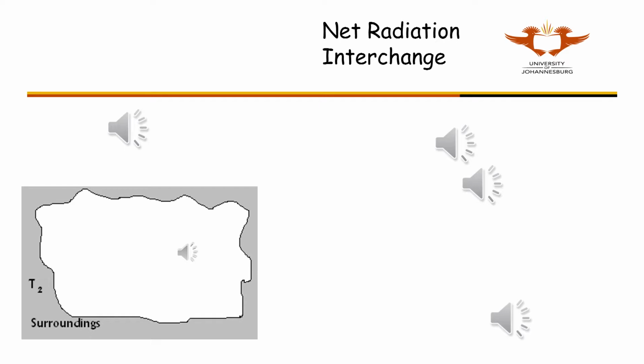Consider a large non-ideal enclosure at a constant temperature T2, i.e. steady state conditions. Heat emitted by the surface will be equal to heat absorbed by the surface. Further, assume that the surface is gray, so that the emissivity and absorptivity are equal. This is probably reasonable, as the radiation is generated at the same temperature as the radiation is absorbed. See the literature on non-gray surfaces. The absorptivity and emissivity are different due to temperature differences of the surfaces involved. This means that the radiation in the open space, G, is equal to sigma times T2 to the power 4.